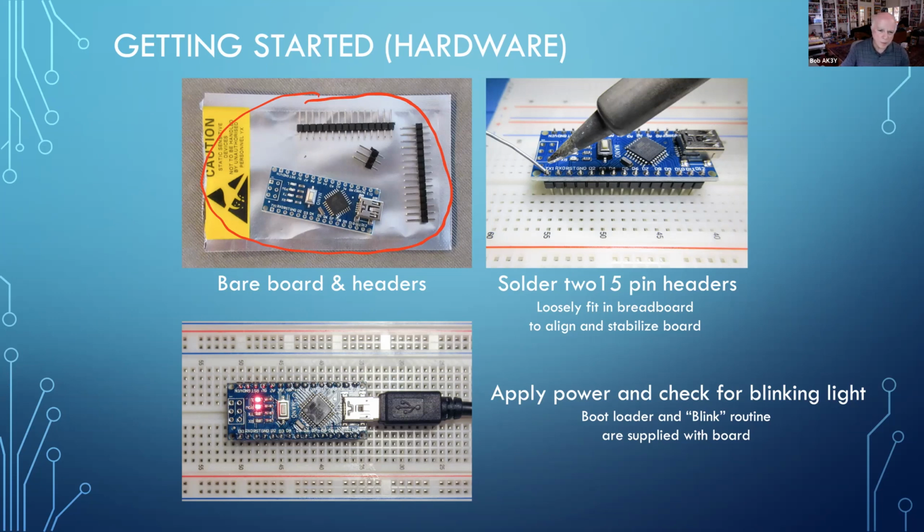The real problem became with the little USB chip. There's an FT232, which on the original Italian Arduinos was being used for the USB interface. On the clones, particularly the Chinese clones, they use a different type of serial interface. It's a different chip, which requires a different serial driver. Not a big deal, but you need to be aware of that when you're programming it.